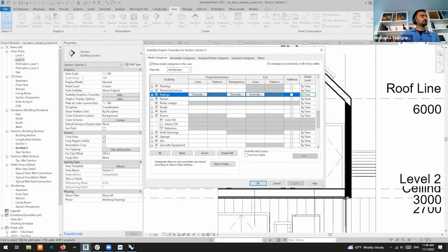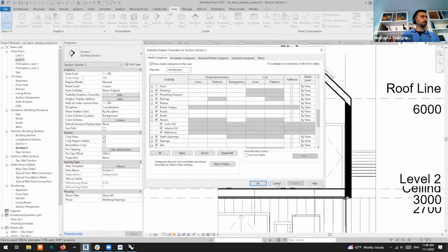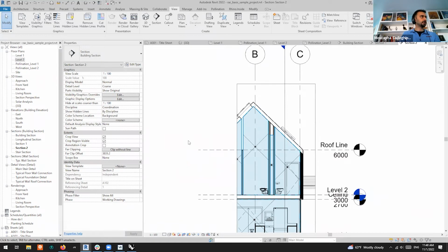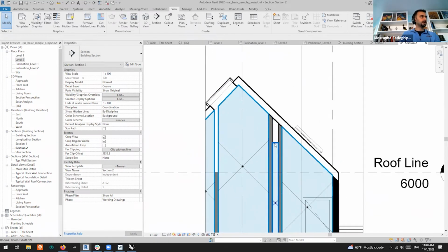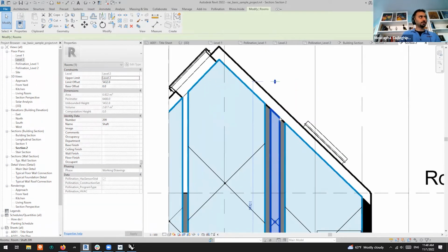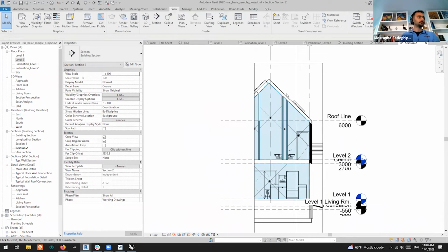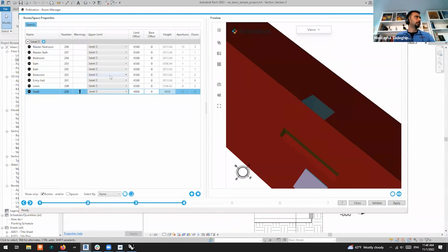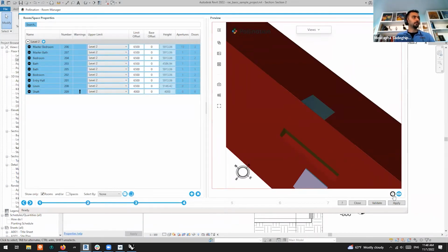We should probably do something similar to what we do for floor plans to quickly make this possible, so you don't have to do it manually. But this is what's happening. This ends up here, so this time I just drag it up. And you see Revit stops it here because this is a room bounding element. So this is done. Let's go back here. Oh, don't touch that. And do reload.